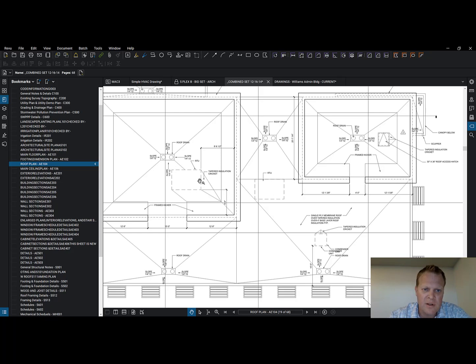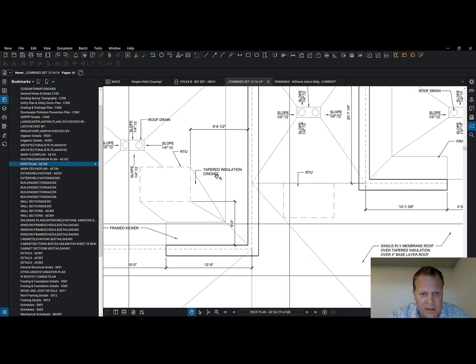This rooftop unit, it's in the way of water going to the roof drain. And so think of snow and stuff like that, slush, snow turning to slush, and then back to freezing again. And imagine that sort of sliding along right here. Well, if we don't do anything about it, do you see how they have this tapered cricket insulation right here? The architect already figured it out.